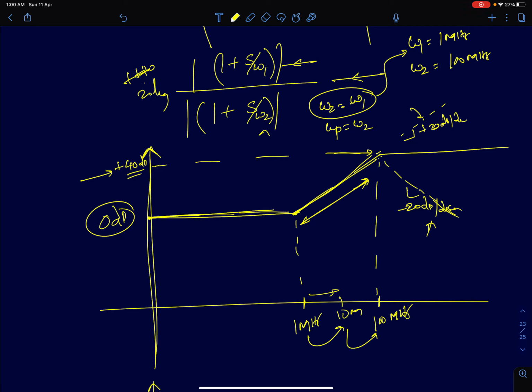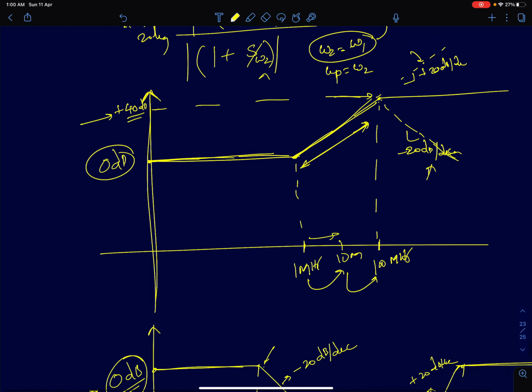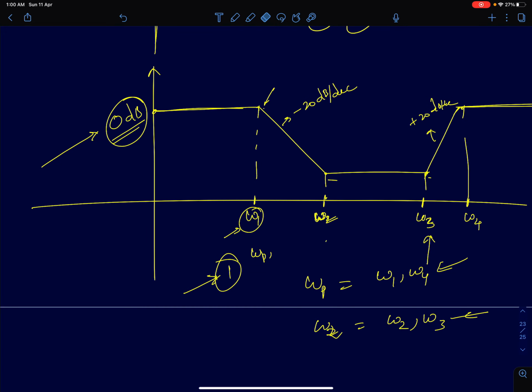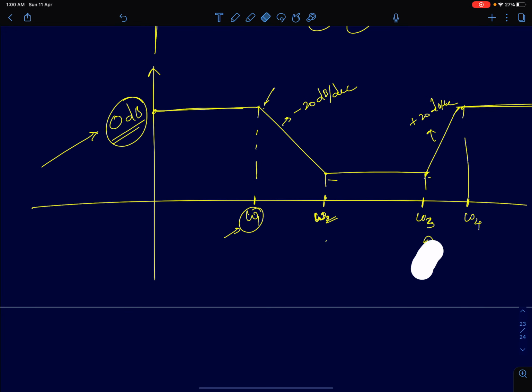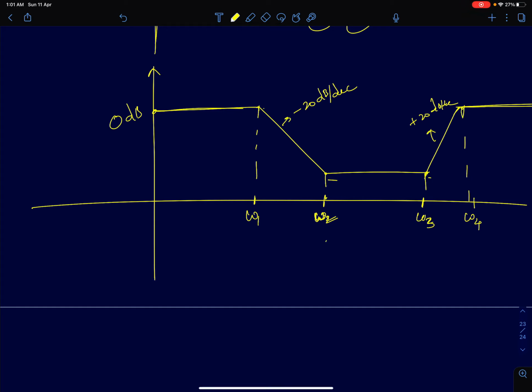So now we were able to plot a transfer function and also mark the steady state values, the infinite frequency and low frequency values, and also show the location of poles and zeros in the frequency response graph. In the same way, given a graph, we should be able to predict poles and zeros, and we should be able to write a transfer function. Now this is the transfer function that is given to us. From this, we should say what are the poles present in the system and what are the zeros present in the system. So start from omega equal to 0.